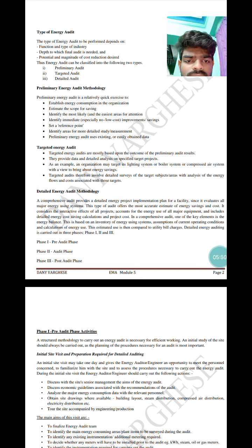In a comprehensive audit, one of the key elements is the energy balance. Here, the main theme of the energy audit is to maintain the energy balance. This is based on the inventory of energy using systems, assumptions of current operating conditions, and calculations of the energy use. This estimated use is then compared to utility bill charges.